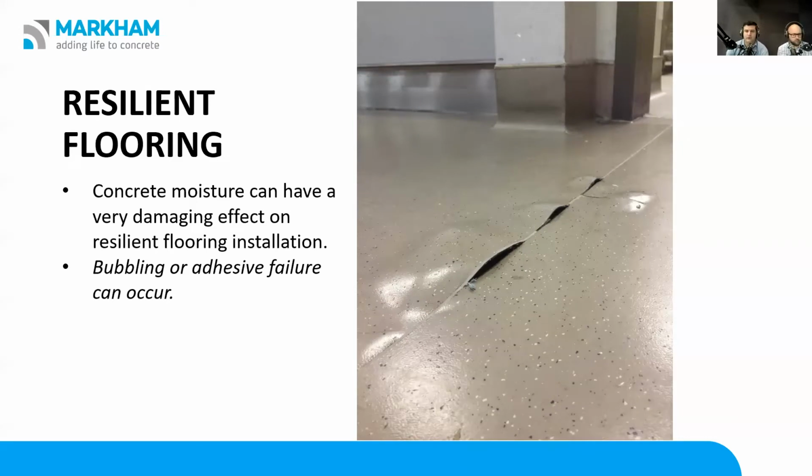Obviously, that's a worst case scenario. But in that case, those floorings have to be removed. The slab has to be re-prepped, the moisture issue dealt with, and then the flooring relaid. So at this stage, it's a very costly exercise. There's a lot of cost and also time, not to mention damage to your name and your professionalism as well. So by dealing with that moisture as soon as possible, and any of those damaging effects that can happen later, getting rid of that as soon as you can in your construction process is obviously the best way to do it.